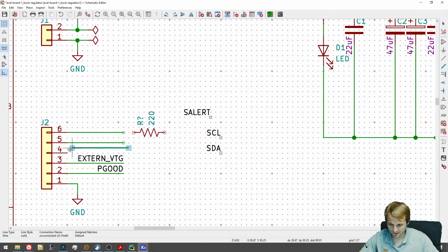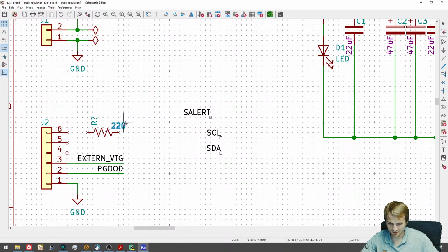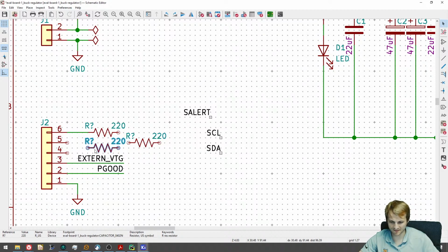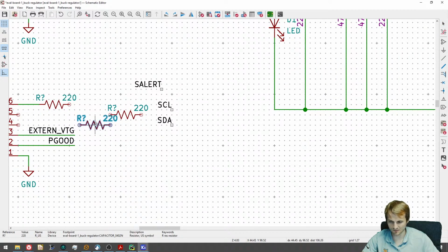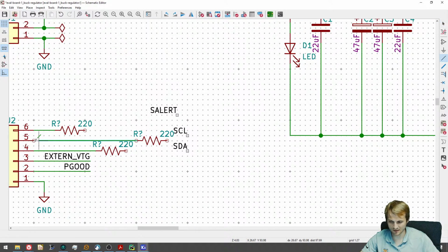Oh boy. And I know I had just said it was weird to me that they didn't have an RC before I realized they did, and now I'm just putting an R. It's true, but since this is from the outside world, what we're more worried about is noise from ESD or some sort of garbage from outside, which a series R will work for pretty well. But yes, if we could put a capacitor on these lines also, that would be amazing.